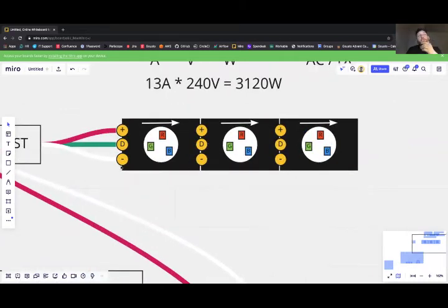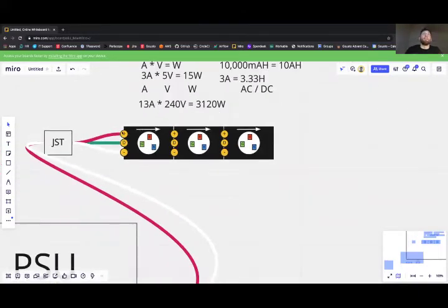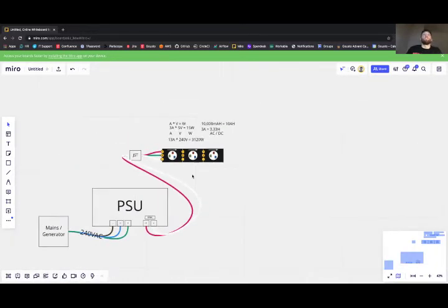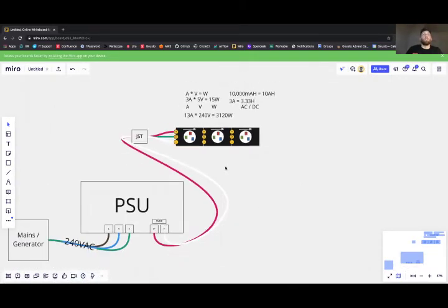So in essence, you can think of these LEDs as being connected in parallel. It's almost as if this positive wire exists along the top and the LEDs fan out from there, and then the negative wire coalesces at the bottom. So this is already a complete circuit and it will turn on.